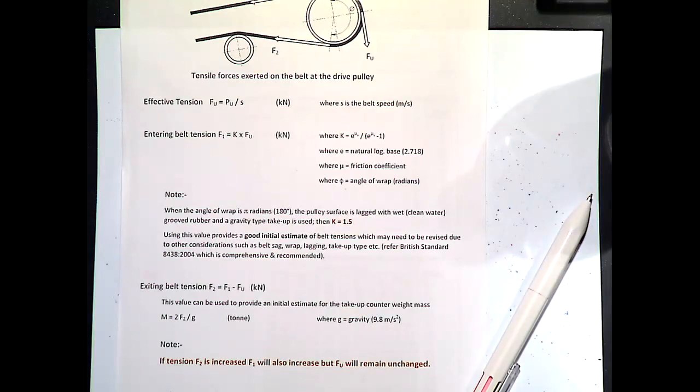Now this one here is pretty tight. You can see there's not too much sag there, but mind you, at the moment it hasn't got any material on, so we don't know. That thing there is to keep the belt on when there's strong winds. The belt might go off to the side, but you don't really want it to go on the ground. But coming down here and starting to go around corners, it starts to get interesting and a bit counterintuitive. Here is a conveyor going around a corner, but the belt wants to come inside, whereas the material going along wants to get flung out on the outside.